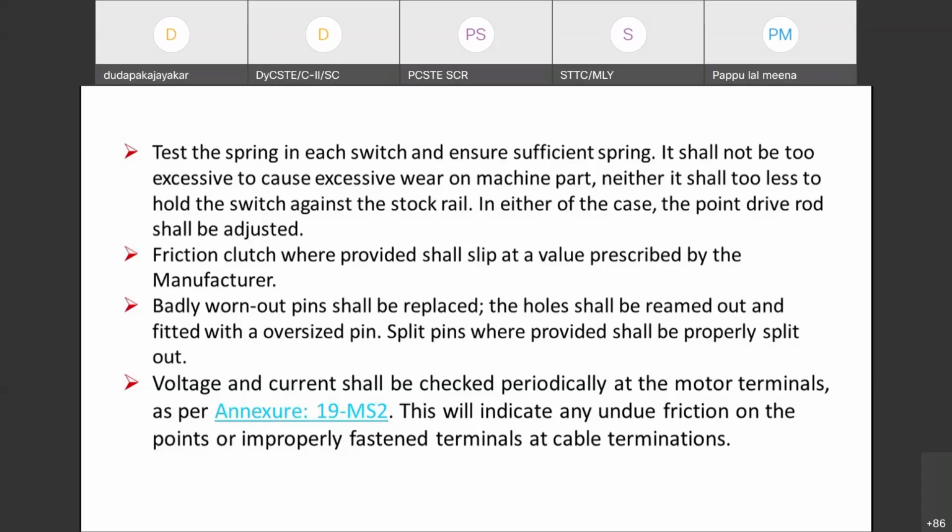Lubrication and greasing of gears, the cleanliness of the commutator, and visual checks. The contacts should be checked for proper adjustment and contact pressure every fortnight. An obstruction test with a 5 mm piece is to be done, and packing and everything should also be ensured.